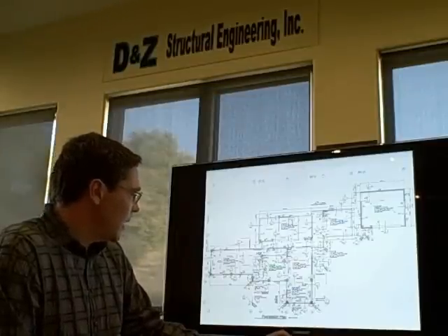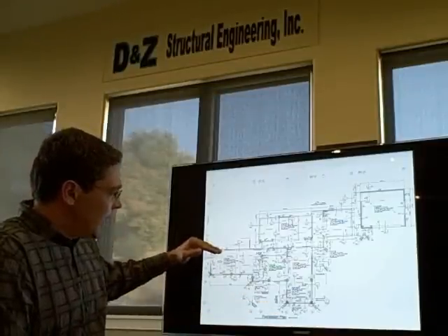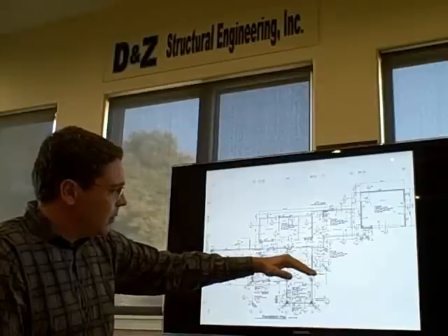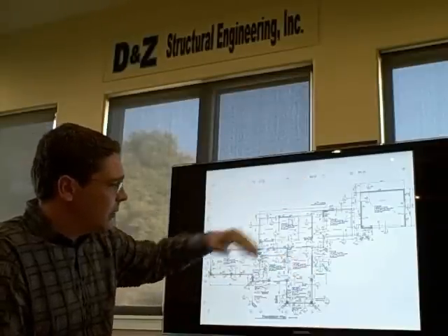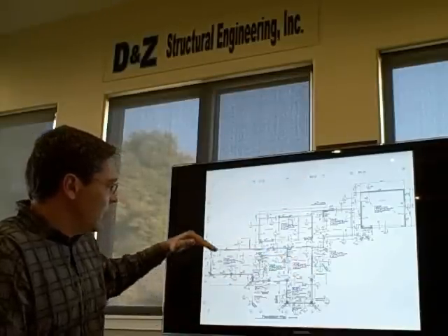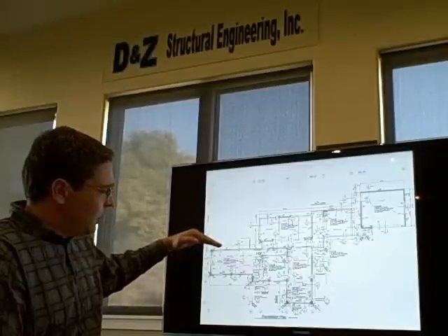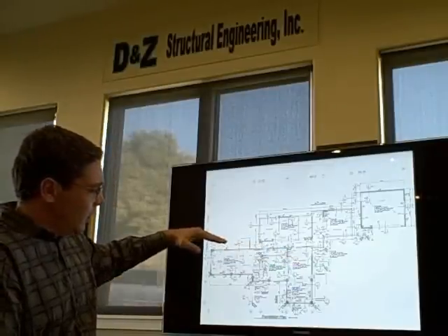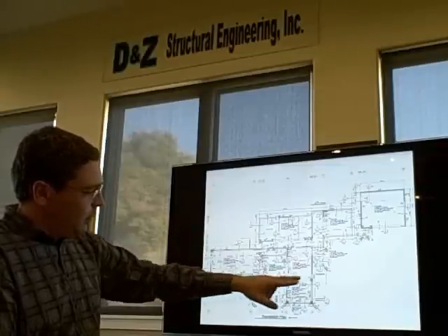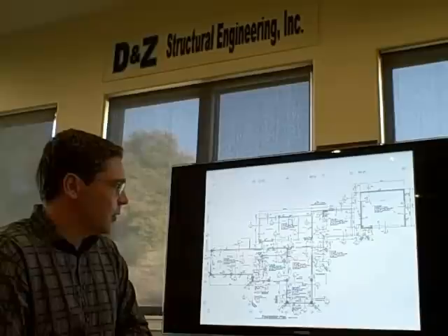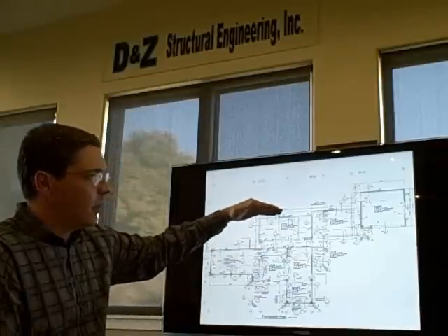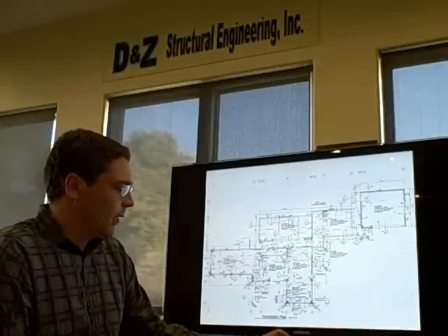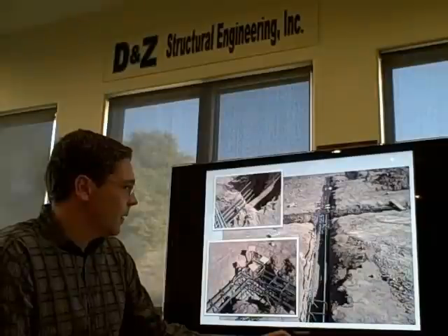It's the layout of a house where a portion of the house is on bad soils and the other part of the house is not. So we've done this many times where it's usually around the cut fill line of the property, where when you're in the fill area we'll be supporting the structure on caissons. When we're in the competent cut area it can go back to conventional construction.